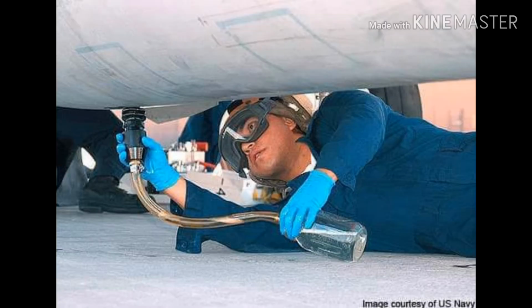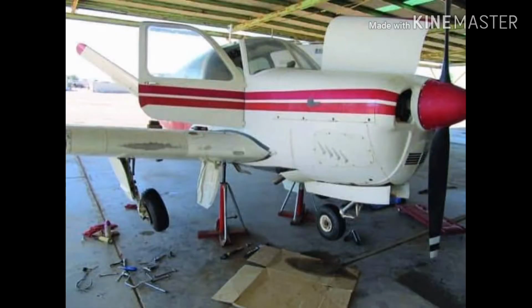The second cause is improper servicing. A-checks are done after 125 flight hours, depending on the type of aircraft and aircraft cycle of takeoff and landing, and take between 20 and 50 man-hours to complete. A-checks on airliners are usually performed at the airport gate overnight. B-checks are performed on average every 6 months.